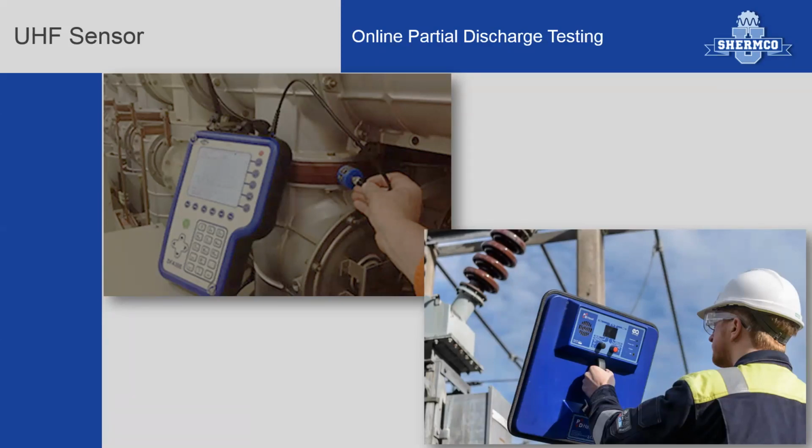The pulse will occur at or near the positive or the negative peak amplitude of the AC sine wave. Thus, the ultra-high frequency pulses will occur at intervals roughly equal to 1/2 the AC cycle time. So for 60 hertz, that would be 1/60th or 16.66 milliseconds in a cycle. So the UHF pulses would potentially occur at half these values or at 8.33 milliseconds.